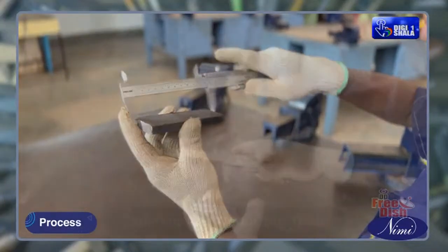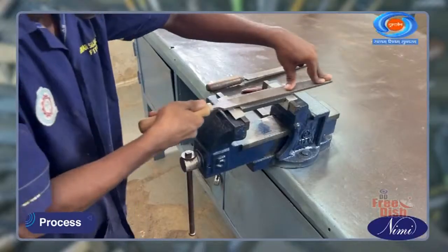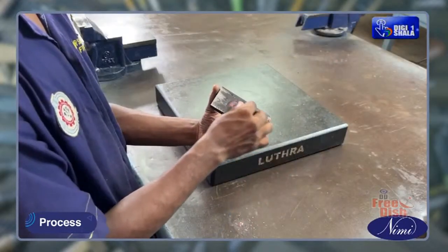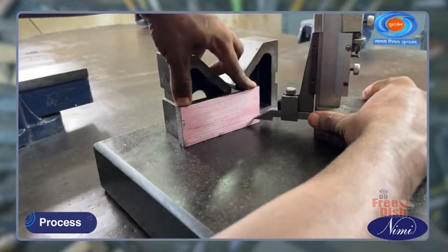Check the raw material for its size. File to flatness and squareness to overall size. Mark dimensional lines as per drawing and punch witness marks.